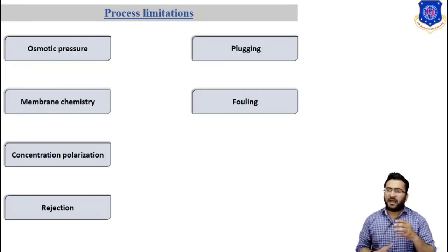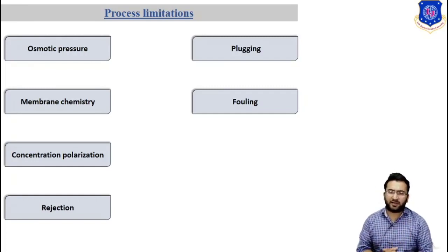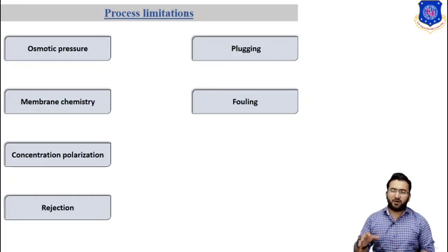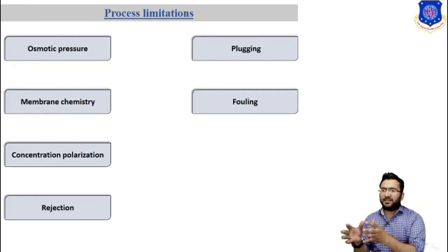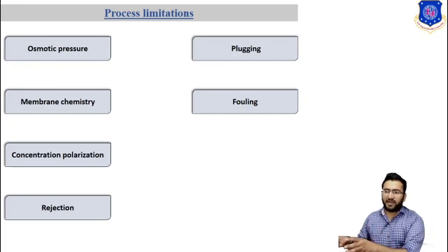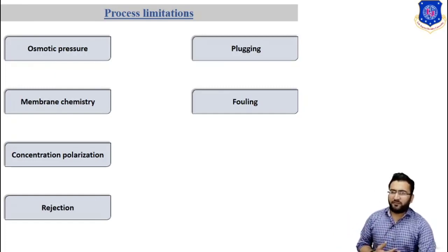However, aromatic polymers have higher pH tolerance than cellulose acetate. Cross-linked polyamides are better candidates for nanofiltration membranes because of their higher permeability. So, from these three groups, cross-linked polymers are much better than cellulose acetate and polyamides. Second come the polyamides, and third, cellulose acetate.